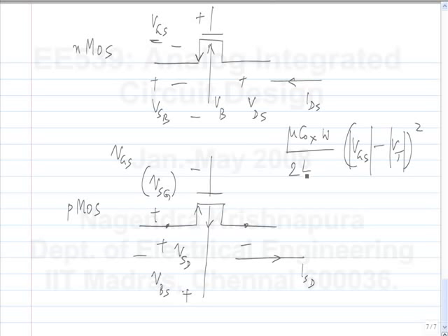Now, what is the other difference between NMOS and PMOS transistors? What's the main difference? Mobilities are different. PMOS mobility, that is the mobility of holes, is about 1/3 that of electrons. So for a given geometry and given bias, assuming both have the same threshold voltage, you will have less current in a PMOS transistor. That also has some implications on circuit design that we'll see afterwards.